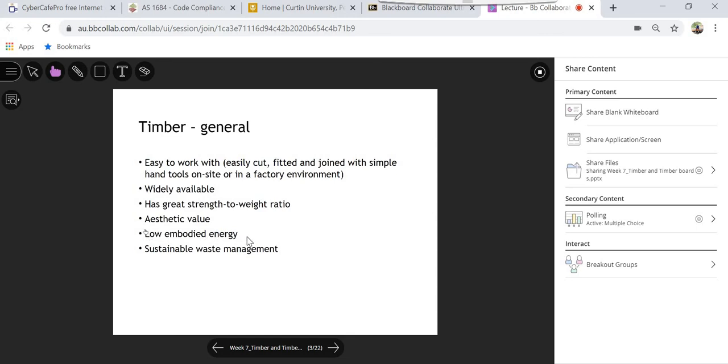And embodied energy is another consideration when it comes to sustainability. Embodied energy means that from the point of taking raw materials up to the installation on site, we have to spend some form of energy to make construction elements from the raw materials to the end product. That total energy we call the embodied energy. When we consider timber, the embodied energy is very low compared to concrete and steel. So that is a good thing about timber also. If we can move towards timber construction, that is actually a great solution.